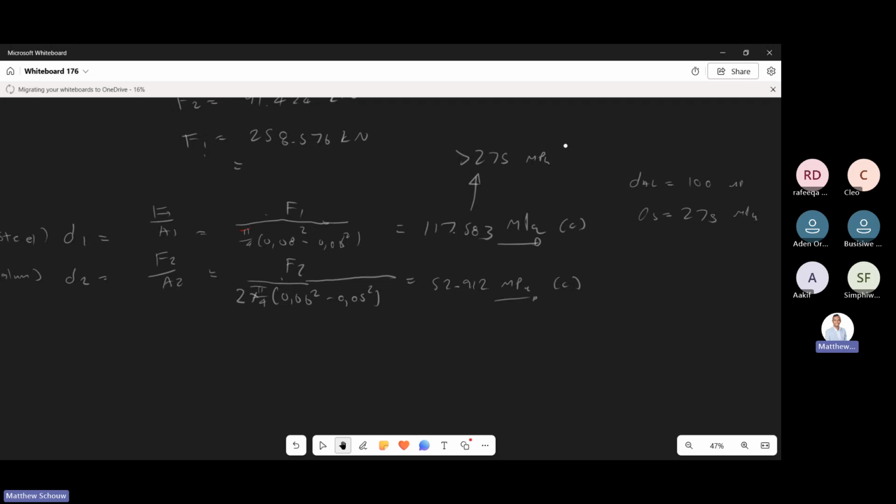But if we change that 70 kilonewton per meter to maybe like 150 or 200 kilonewton per meter, you'll notice the stress values will increase, right? And if it increases above that value, if it increases above the UTS, it'll break. That's the purpose of these calculations, by the way. Yeah. I don't know if I was clear there.